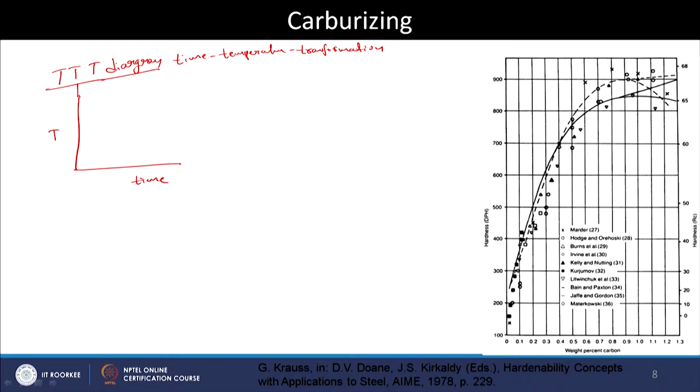and then you can mark the temperature, for example, this can be the A3 temperature, right, and then you have a time scale. Then you will see the phase fields where you get the different phases, for example, such C curves can be seen. This is the gamma, this is also gamma, right, and this is a metastable gamma, because you see that below A3 it should not actually have been single-phase gamma. So, that means it is metastable, and above it is a stable gamma field. And these diagrams tell us how you can construct such a diagram.